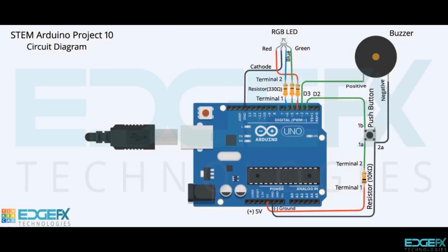To generate the final output, to generate a rainbow of colors, each with a unique buzzer sound. To summarize this step 10, we connect push-button switch, buzzer, RGB LED, resistors, and Arduino such that when the Arduino is powered and we press the push-button switch each time, the RGB LED goes on and off or flashes in rainbow colors: red, green, blue, yellow, magenta, cyan, and white for a specified duration of time, and switches off when the switch is pressed again.